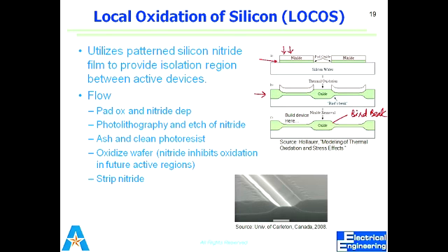One thing for your knowledge: gate oxide is mostly grown by dry oxidation, because it's thin. And for field oxide, if you are not told whether we are using wet oxidation or dry oxidation, always go for the wet oxidation parameters, because field oxide is always a thick layer.